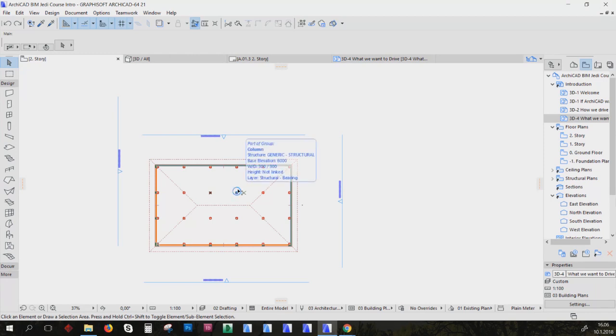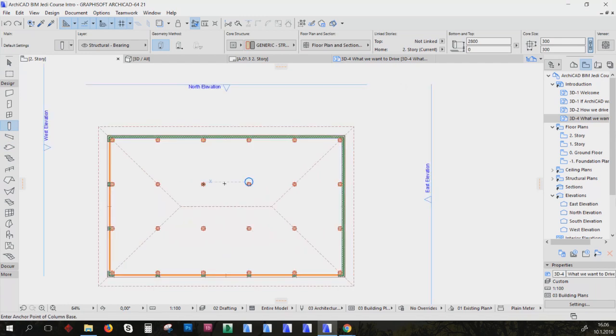Yep. So if we go, we're on the top. So if I wanted to put, say, a column on this roof, Alt V brings on gravity, and that's this little weight thing up here, and it toggles it on and off. Then here we can gravitate to roof, and then I've got that damn shift lock on.